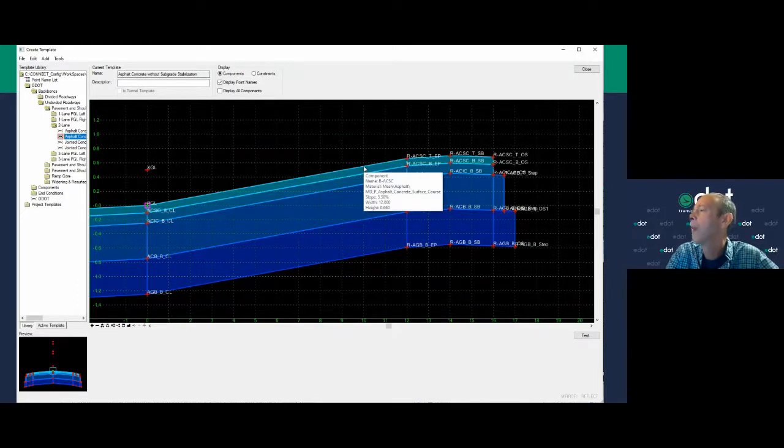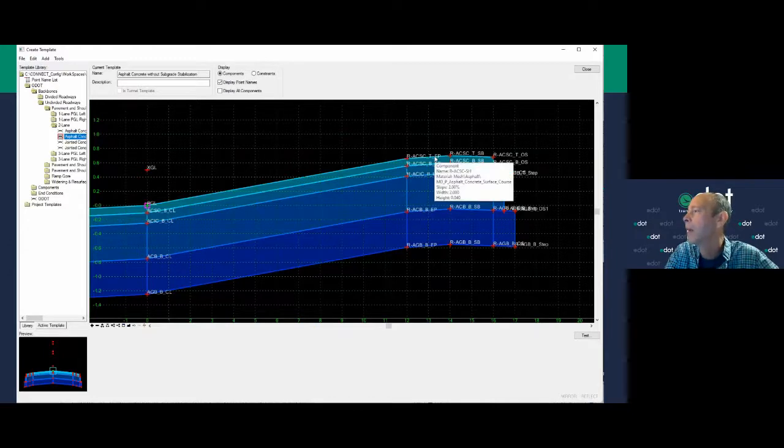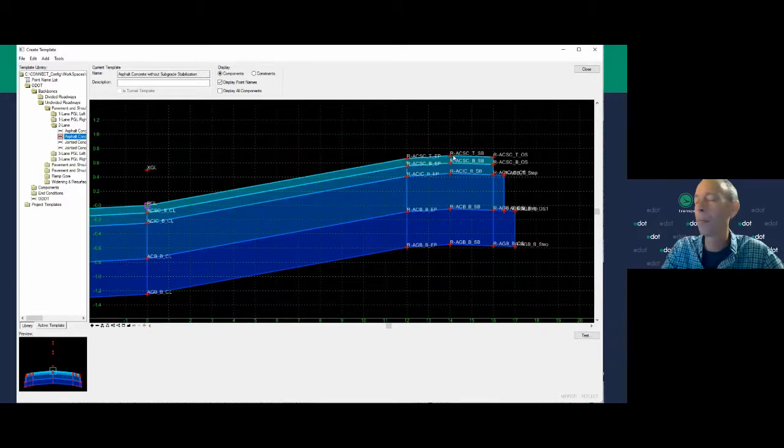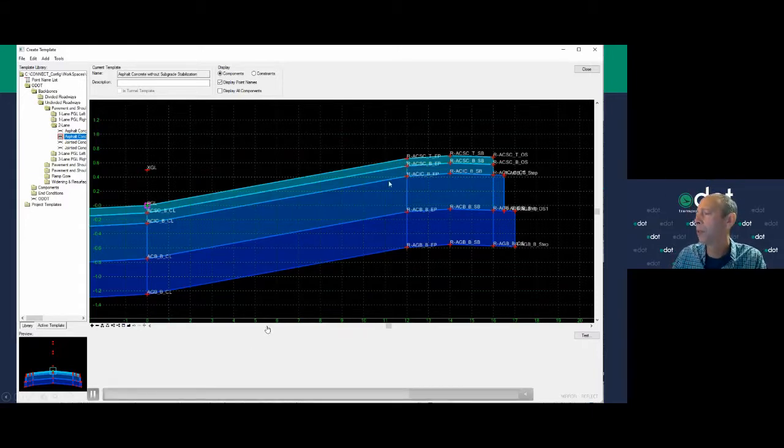I can see there's my 5.5% slope on that lane of pavement, and I can see it's giving me a 2% slope there as it's in the center of that transition up to where that would equal the 6% at a 6% pavement slope. And again, that's not what we would expect to see there. We'd expect to see a -1.9. Okay, so that's just the overview of that rollover lock and how it's defined.